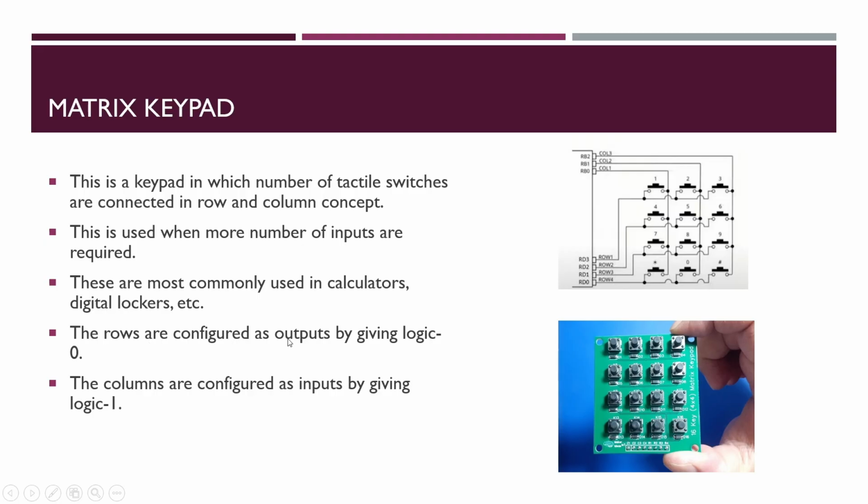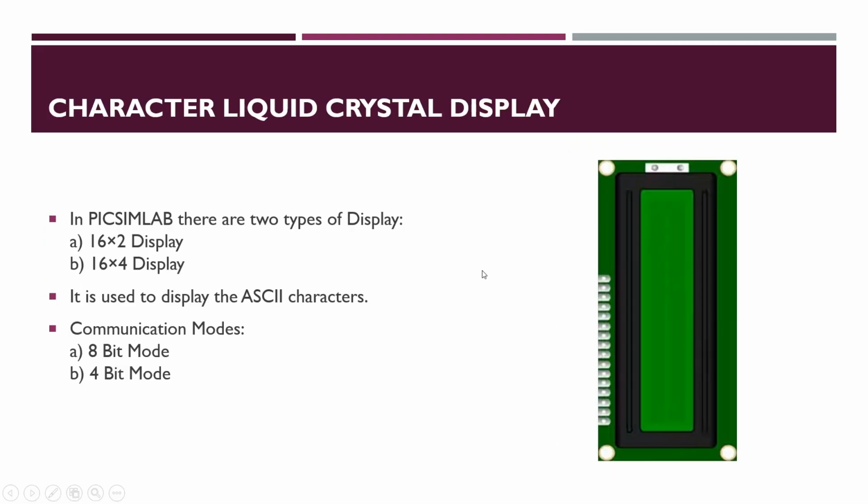The rows are configured as output by giving logic 0. The columns are configured as inputs by giving logic 1.